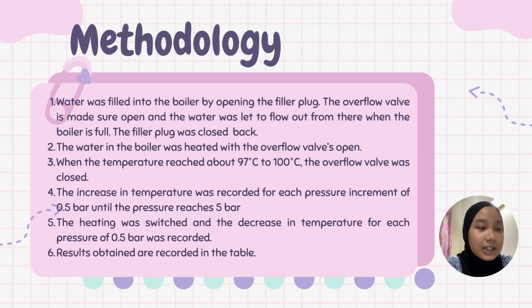So for the methodology, as already explained by Brian about the apparatus and the location of each part of the Marcet boiler, now I will explain how to conduct this experiment. For the first step, water was filled into the boiler by opening the filler plug. The overflow valve is made sure to be open and the water was let to flow out from there when the boiler is full, and then the filler plug was closed back.